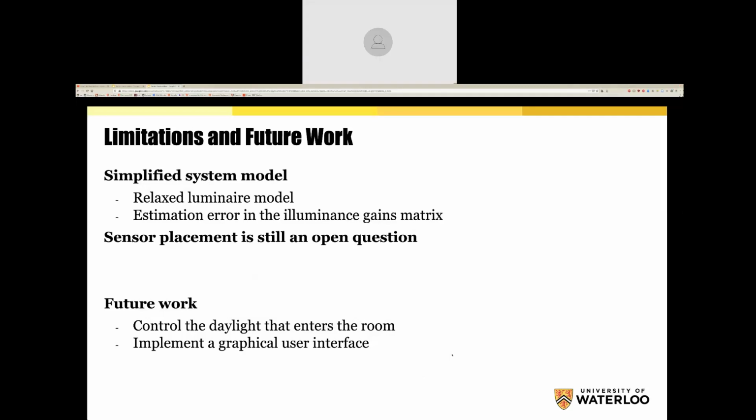Yeah, so, very nice. Thank you very much, Keshav. So, is it necessary to recalibrate the A matrix or is the LED very stable, so it's not necessary? No, the A matrix is recalibrated every 10 seconds or so. And the reason is because we need to just think about it from the RF perspective, right? If you have any kind of mirror or reflection, if somebody wearing a white shirt enters the room, the A matrix changes, right? If somebody opens a window, somebody opens a door, the A matrix changes because you're going to get multipath reflection off of that.